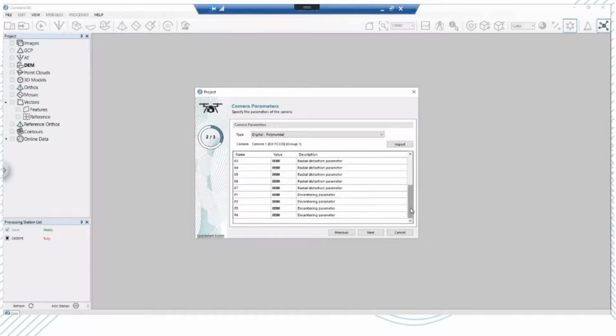So if you were to process that data out and you were to see some error, understand that even though it's a fairly tight metric camera, the calibration that it came with was calibrated in a lab. And in reality, unless you're mapping the inside of a lab, you need an in situ calibration, which is something done in the conditions that you would be flying.